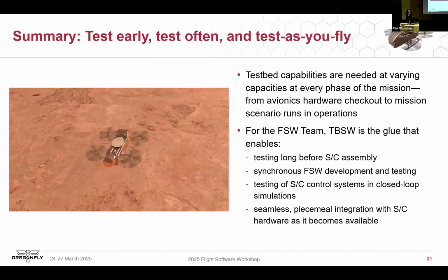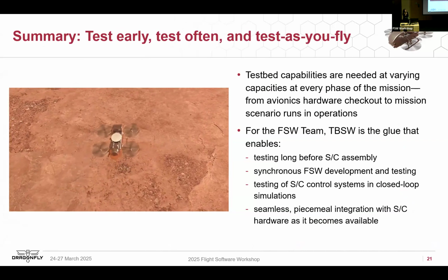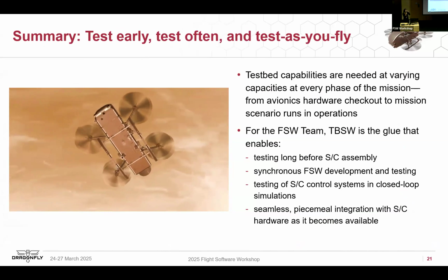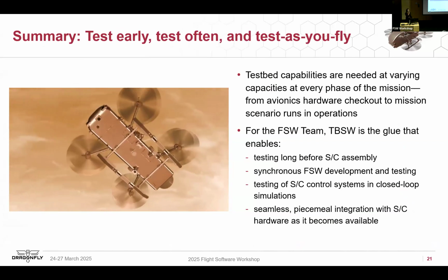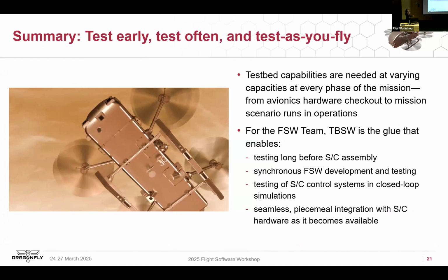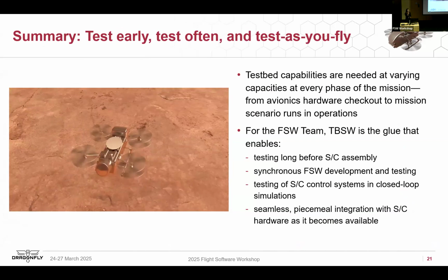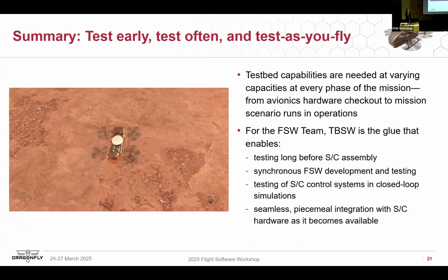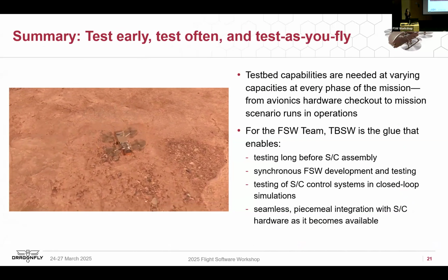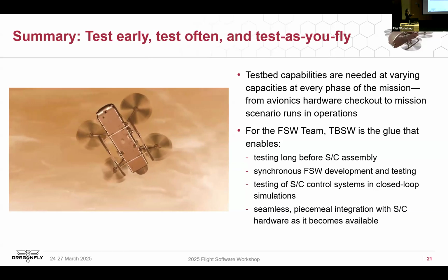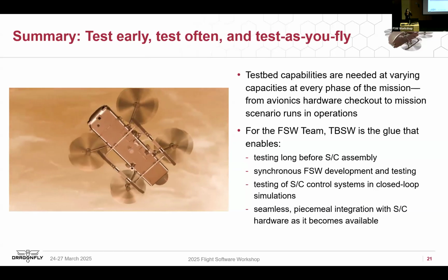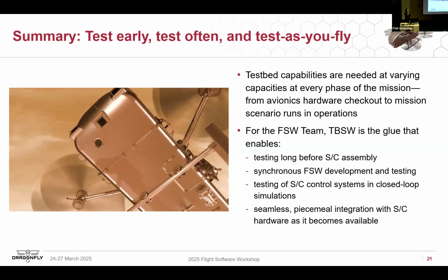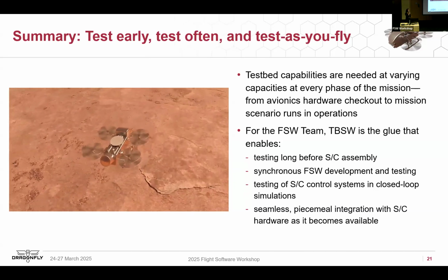So in summary, test early, test often, and test as you fly, and the testbed software is a huge part of making this happen. Testbed capabilities are needed at varying capacities at every phase of the mission, from avionics hardware checkout to mission scenario runs and operations. For the flight software team specifically, though, testbed software is that glue that enables testing long before spacecraft assembly, synchronous flight software development and testing of spacecraft control systems in a closed loop simulation, and seamless piecemeal integration with spacecraft hardware as it becomes available.